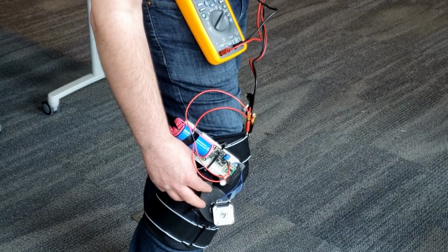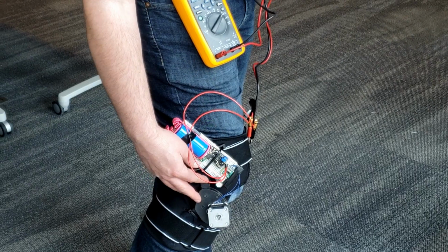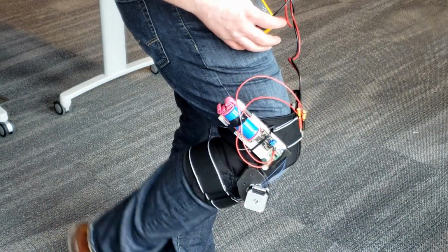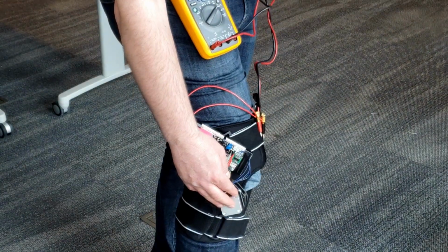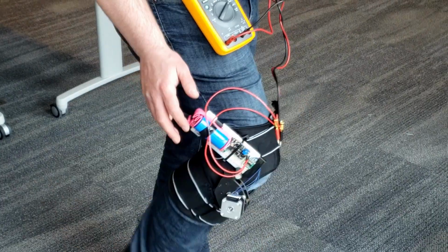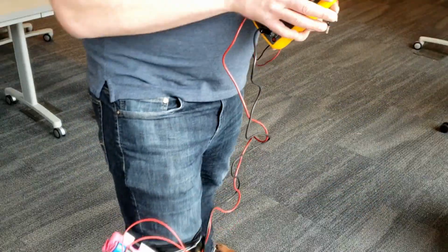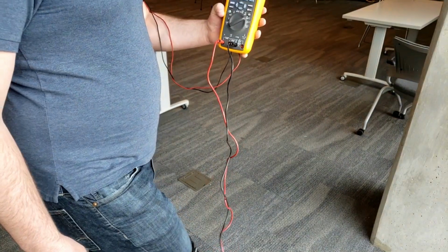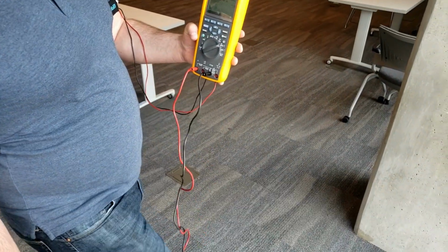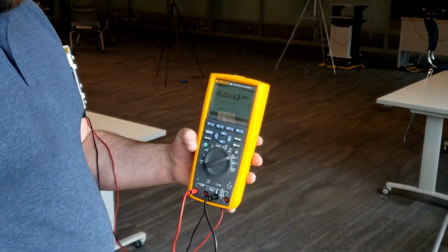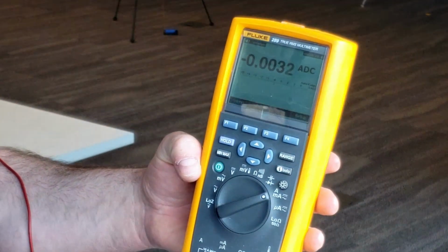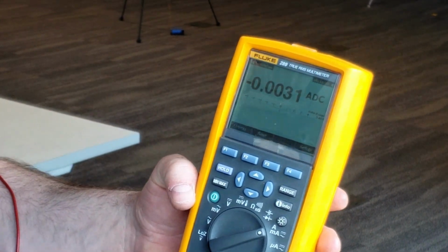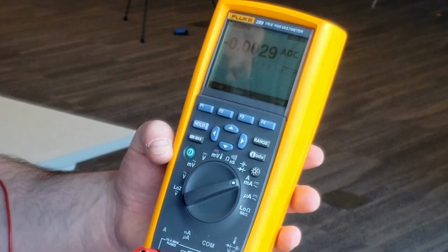So lastly, I'll just show you on this knee brace, we have a carbon fiber nylon 3D printed gearbox with about a 16:1 gear ratio. And as you can see, when I bend my knee, I end up moving this stepper motor and we end up generating power. And we can take a look here that as I'm just pumping my leg here, I'm making a small amount of current. There's some room for improvement with a greater gear ratio, but for now it still demonstrates that we can make some amount of power here.